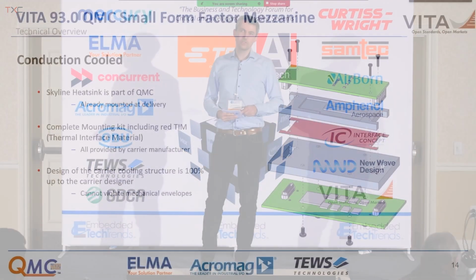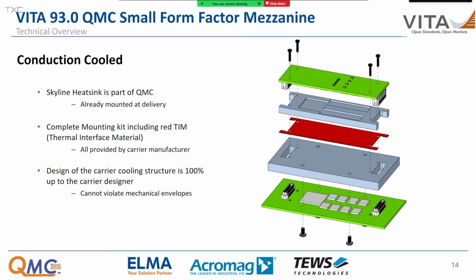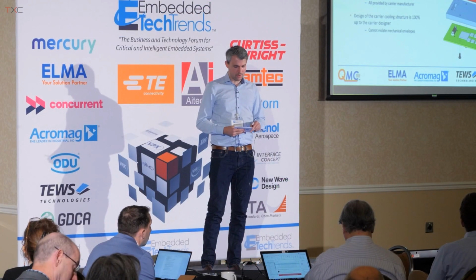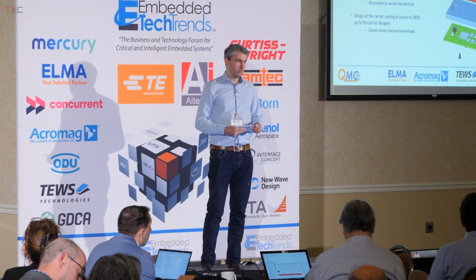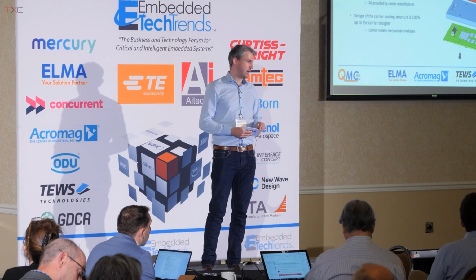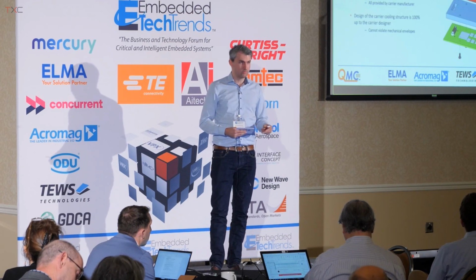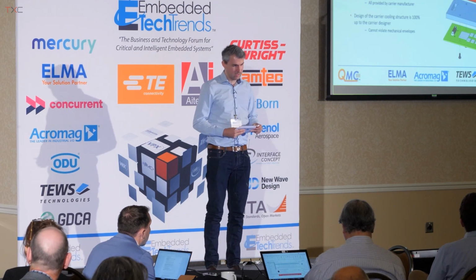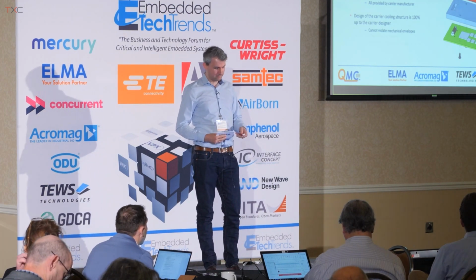One thing I want to mention in particular here is the thermal interface material in red, because it extends over the whole QMC and provides a direct high-performance thermal interface to dissipate the QMC's heat. And that is really important and critical because of the amount of power dissipation you will need for QMCs, and also a great advantage over traditional mezzanine concepts. But more towards the power budget later.